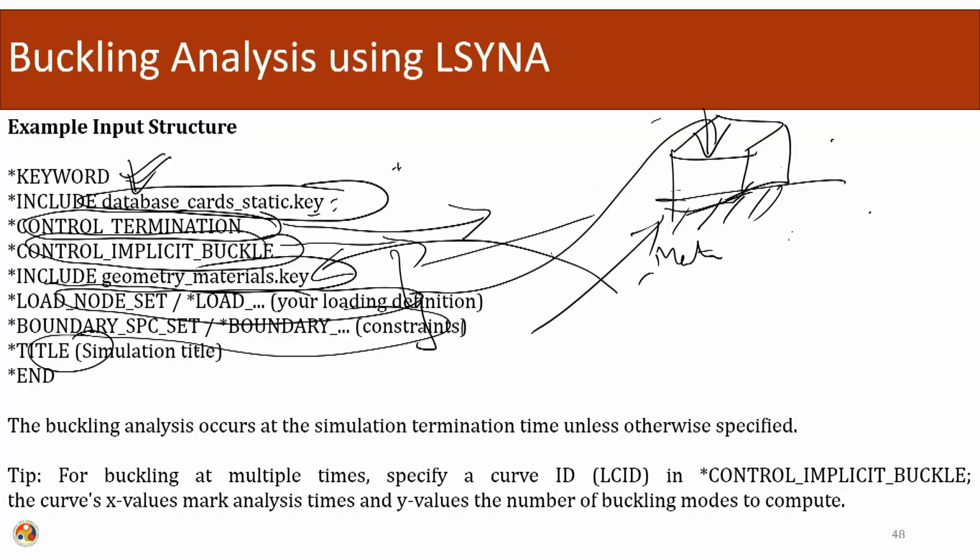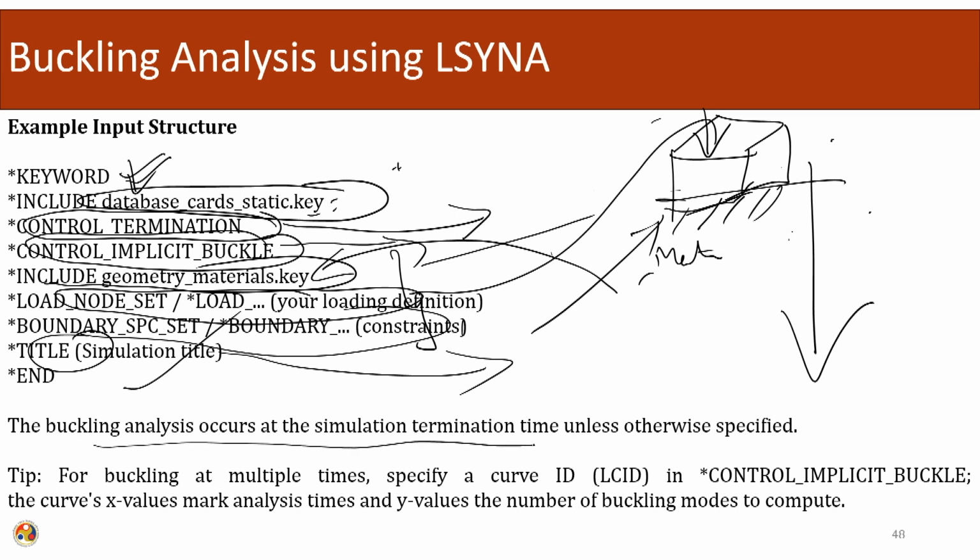And this is the title of the simulation, we can put in any title, and after that we perform the entire simulation in LS-DYNA. The buckling analysis occurs at the simulation termination time. This is the control termination, which tells us till how much time we want to run it. So it will run until this specified time.